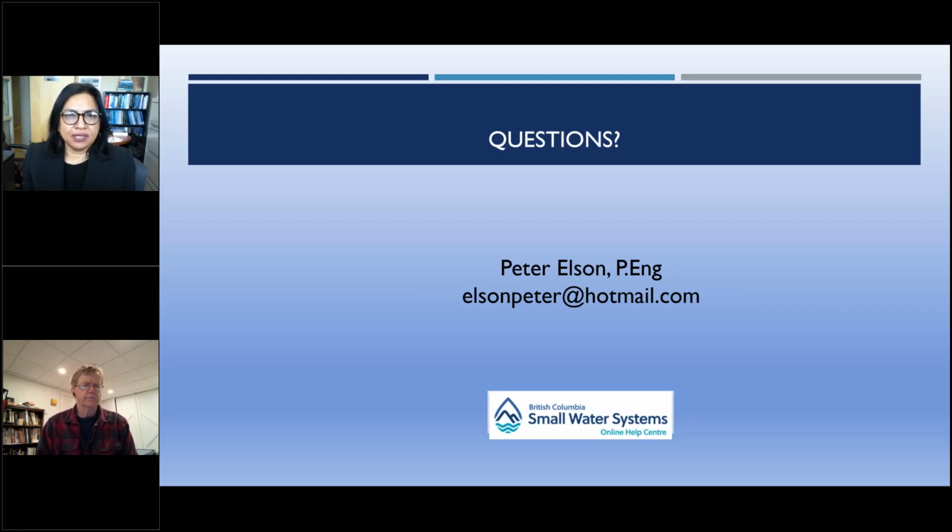So if you're treating for manganese, do you still check for manganese residuals in the distribution system? Yes, you do. You still check. It's a good idea to check, particularly if you just put in a new system. You want to make sure that you're getting the treatment that you hope you're getting. But then on an ongoing basis, you want to make sure you're checking, because manganese treatment systems can fail.